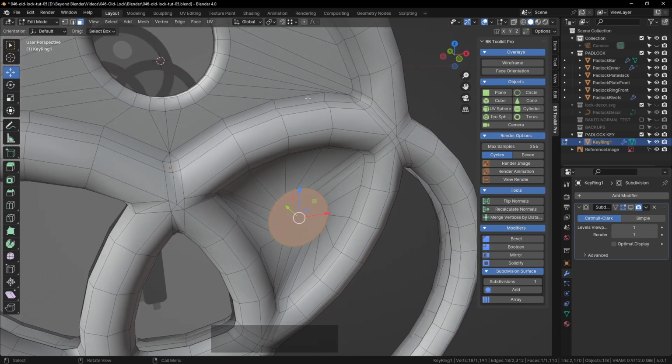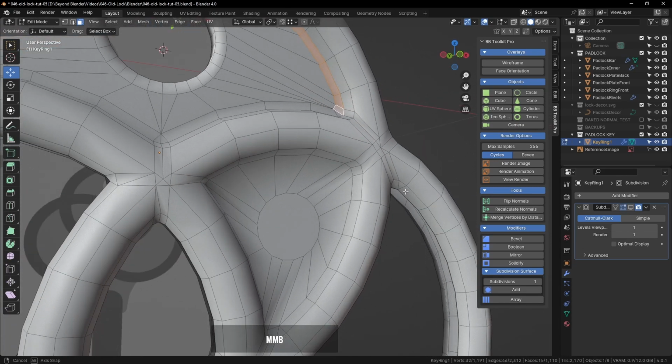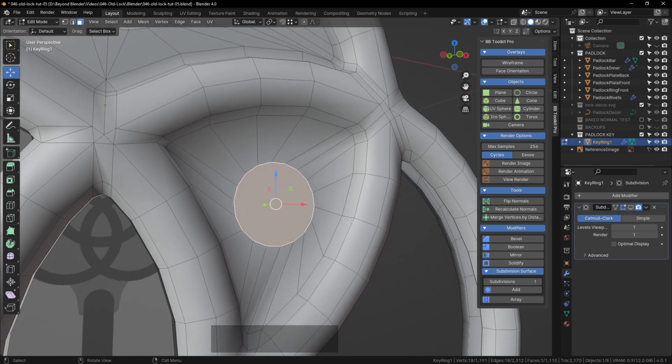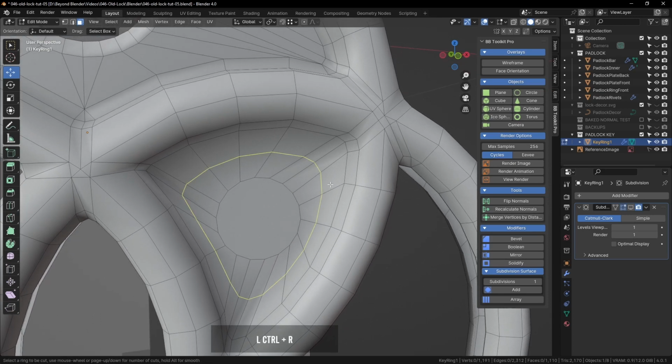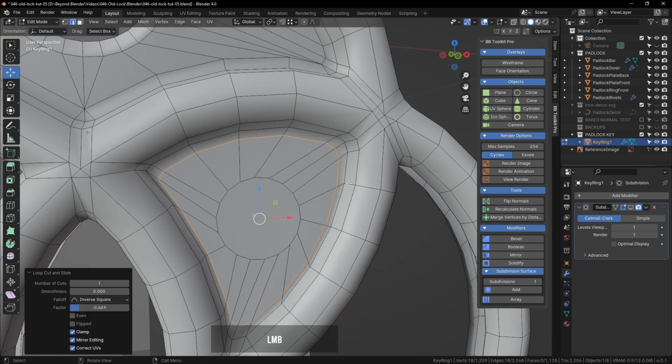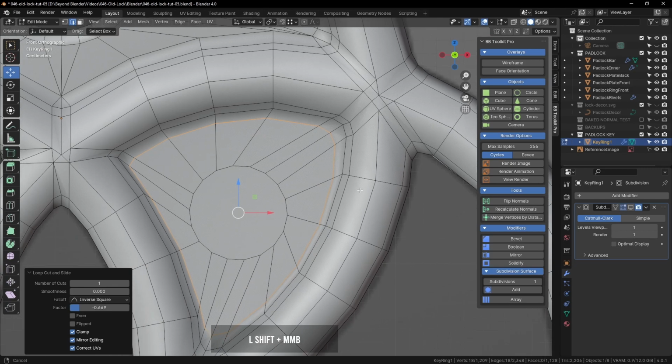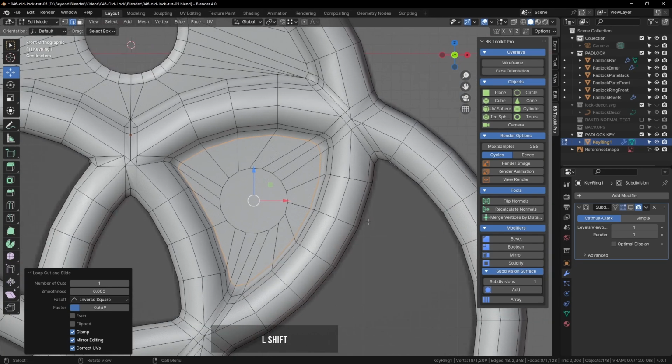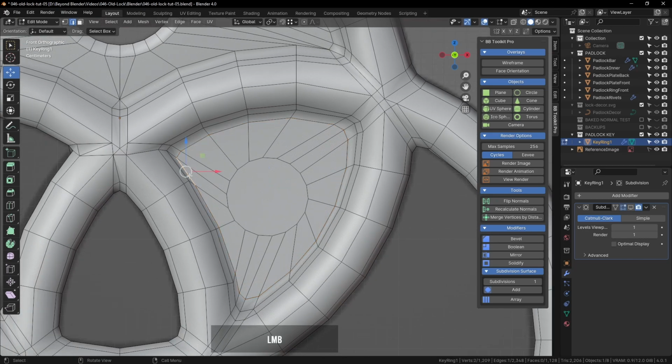Let's have a think about how this is going to work. This is what we're after. We've got these edge loops that run along the outside, or just the inner side there, inside of that. So we just need to create another edge loop to support that, to really help clamp this. And I'm pressing the B key for boundary, or E for even, I think it is, or I think it's B, I can't remember now. And that just makes the edge loop kind of conform to the nearest edge loop.